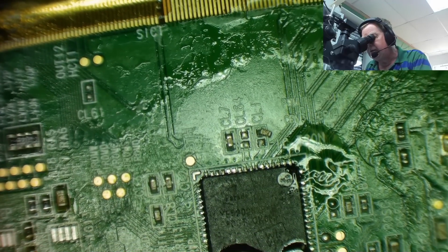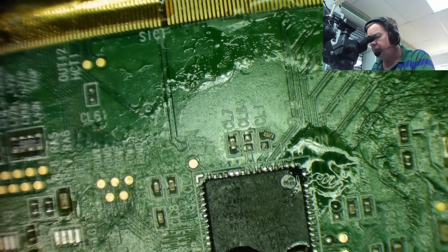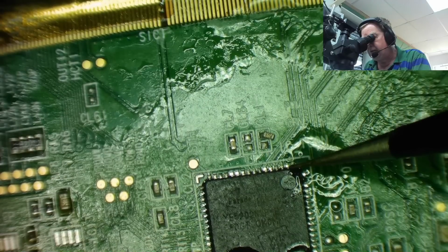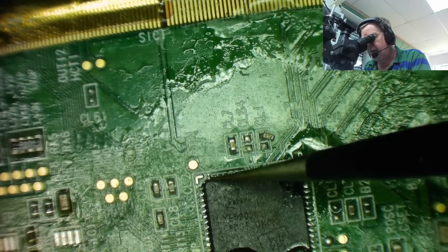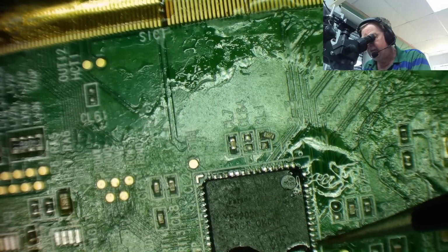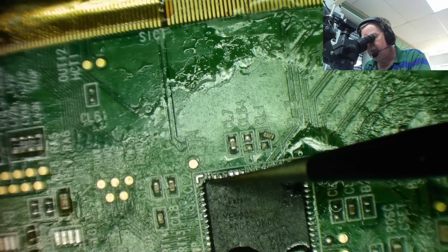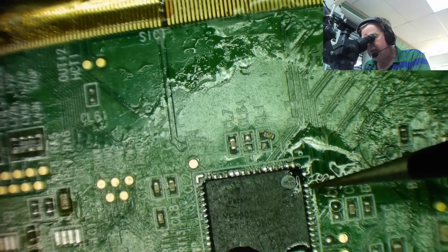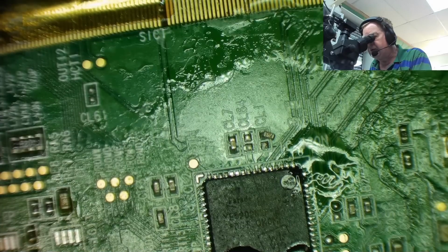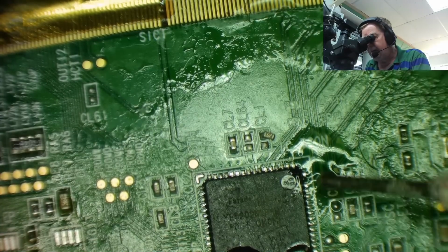I've just tried to tag a couple of bits of solder on the various corners to hold it in place, and tapped it to check it's not moving. I can see the legs are lined up, or nearest damn it lined up with the pads. So I think now it's going to be a matter of going around this chip with some flux and some solder, and let's see if we can actually get it into place.